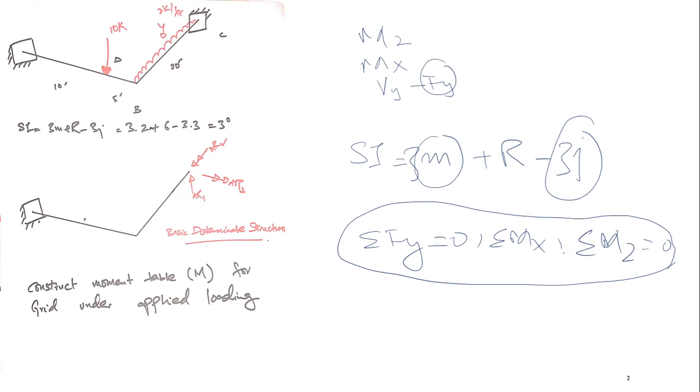Okay, I found it. Here it has two members, so this is 2, and we have one joint, two joints and three joints, so it is 3 here. So it comes out to be 3 degree. It means this grid is statically indeterminate to 3 degree. It means it has 3 extra reactions, or it should have 3 redundant actions. So I have to remove one of the supports to make it determinate.